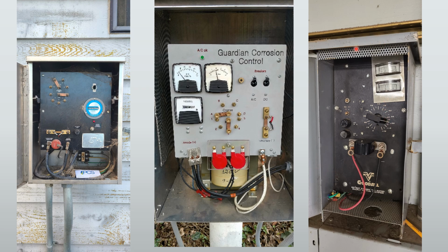The Goodall, this is another rheostat one that I was talking about. So this is a dial adjust unit, 0 to 120. I'm not actually sure what the units are, but they're great little units. It goes up to 50 volts on this one, 5 amps. The gauges are actually curved, so you do kind of have to bend your body around to get an accurate reading on where it's at. AC, DC, fuse, great little systems. They make really good test rectifiers because you can adjust the voltage output so quickly.